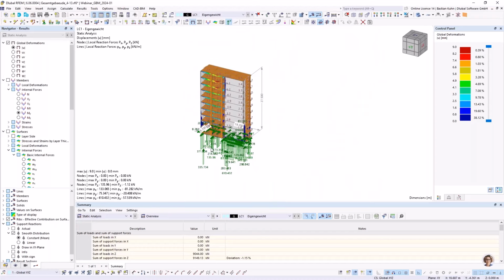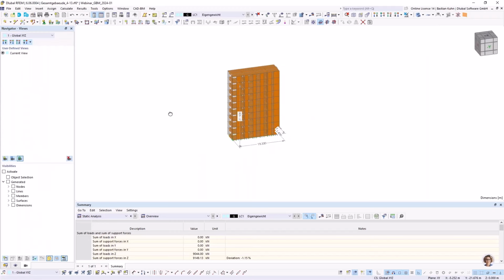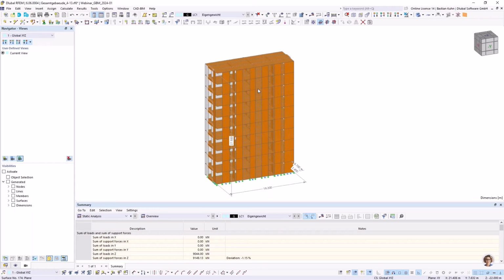But the problem always is when you do calculate such a structure in this way, it is not the reality. In the reality, such a structure would be assembled from the bottom to the top. And now you are calculating from the top to the bottom, which is, roughly said, wrong. And you should not do it, or you should find a way to regard settling of the structure during the assembly. What is when a stiffening element is failing or whatever. There are hundreds of things you should regard, and when you just calculate the whole building, it can become extremely wrong.